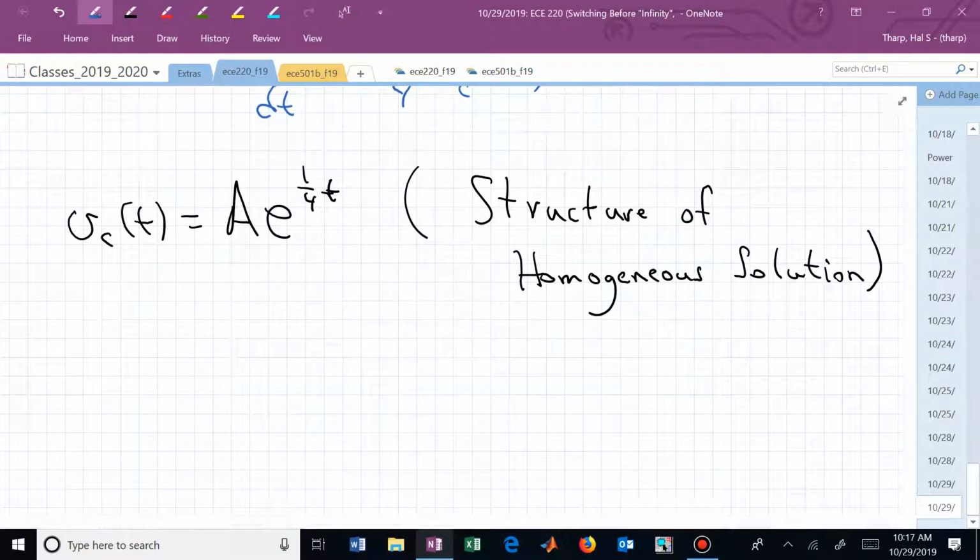And what do we know? Do we know anything more? A is an unknown. Can we find it? Capital A is an unknown voltage. We have the exponent, and this exponent should be making us a little bit nervous because there's no minus sign. Now as we plug in bigger values of t, what's happening? We have an exponential growth. And that's from what? Having that negative resistor. It's now not dissipating energy, it's now helping things grow.